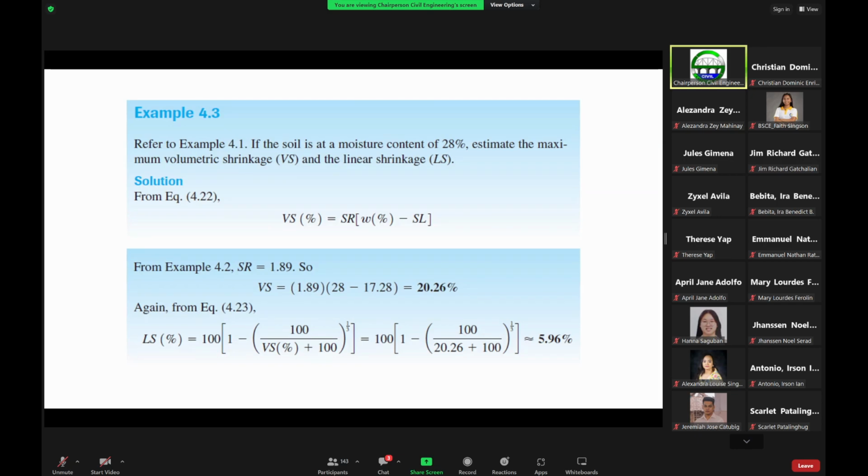Any questions so far? Again, in practice, we use the first 30-meter depths for the soil profile for seismic assessments.